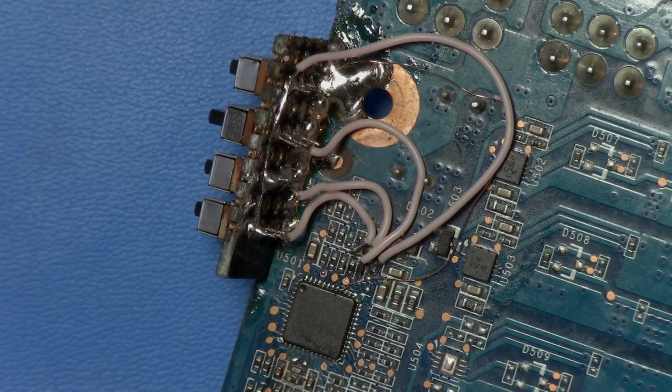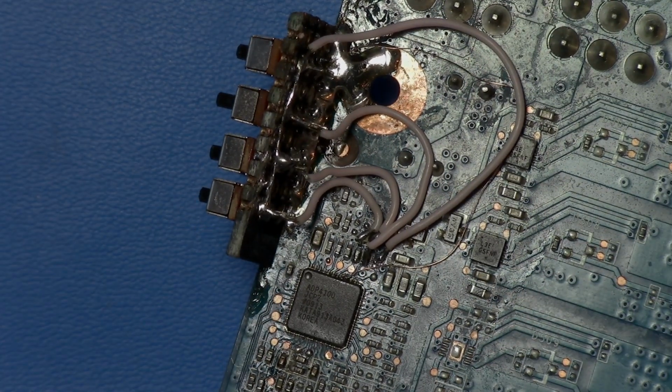So when I implemented mine this way, all I did was VIDs 5, 4, 3, and 2, I believe. Yeah, I think that's it. 5, 4, 3, 2. I don't need much resolution, actually, in my personal opinion. If I wanted more resolution, I'd add potentially a trim pot in addition with it. I might still add 1 and 0, but honestly, the 4 switches are probably good enough for me most of the time. And yeah, you don't really need a ton of resolution, honestly. If you ever mess with a trim pot mod, you already know that your effective resolution often isn't that good, and that is often good enough anyways.